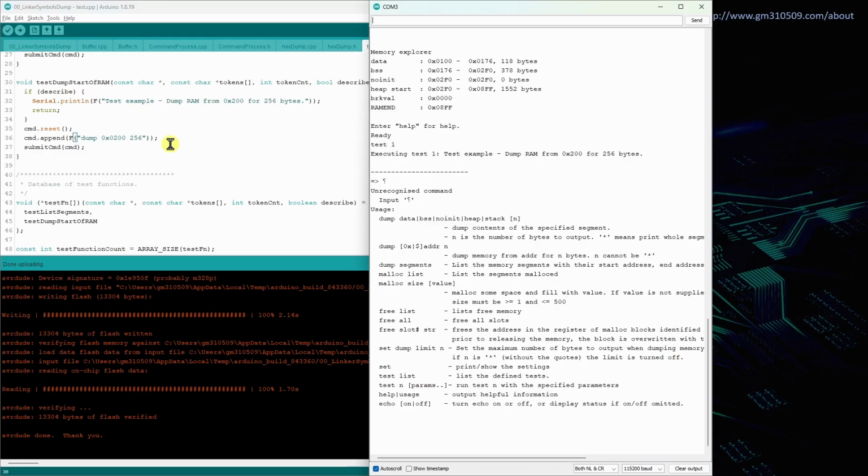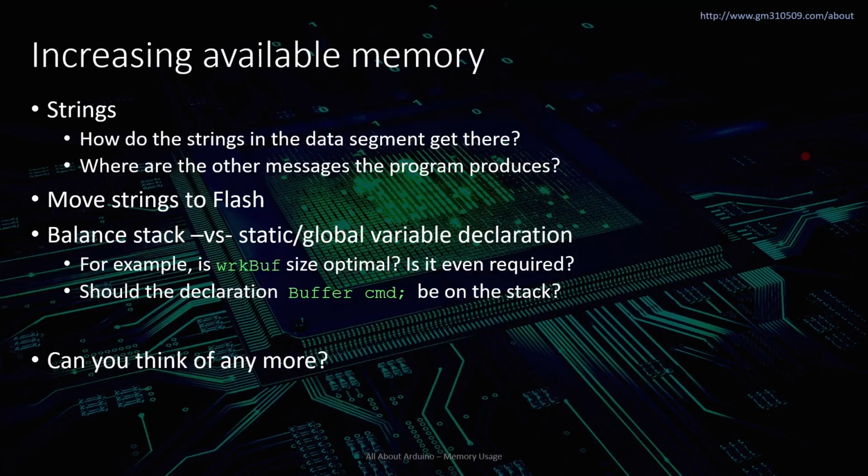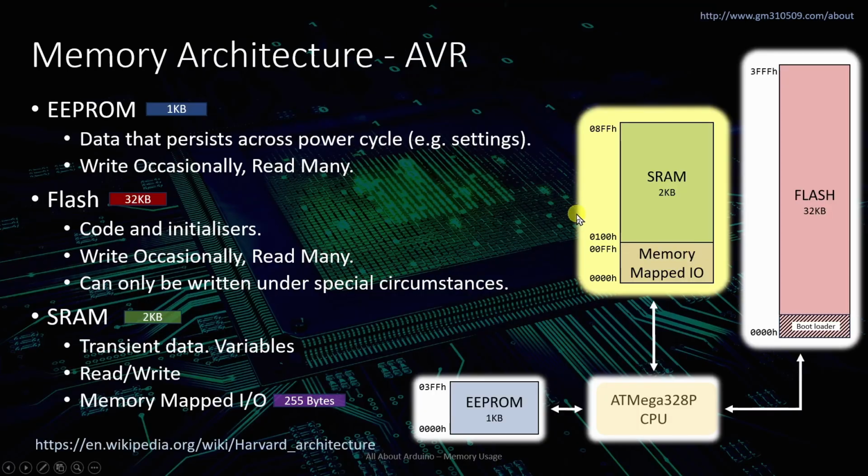And the reason for that is because I moved this into Flash, it's not understanding that the address that's being given is in Flash, and therefore it needs to use a different set of instructions to extract that memory. And this goes back to that these addresses are reused. So we've got a 100 here. Let's say the string was there. There's also a 100 here.